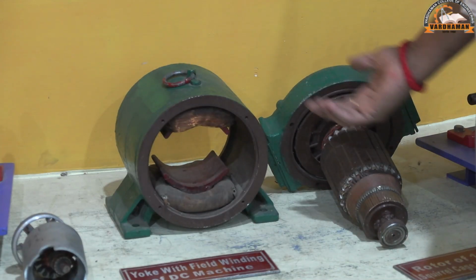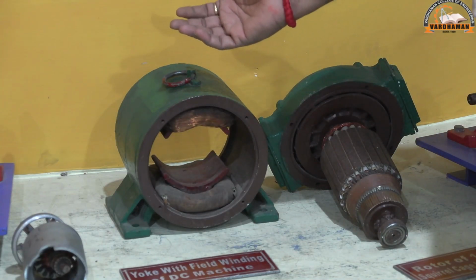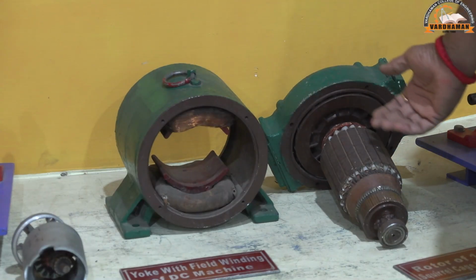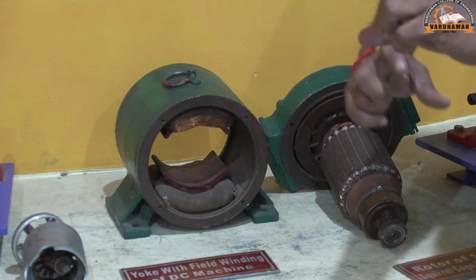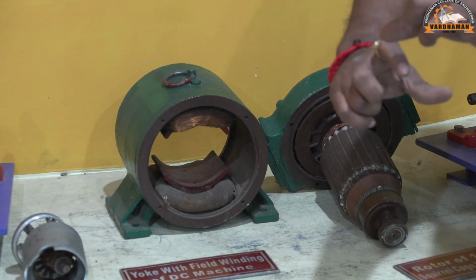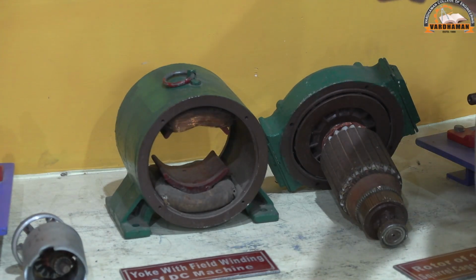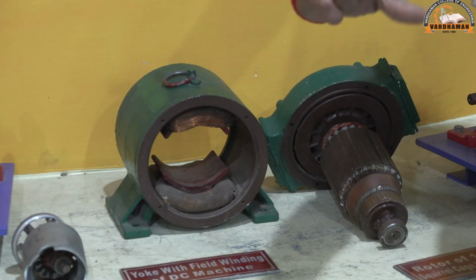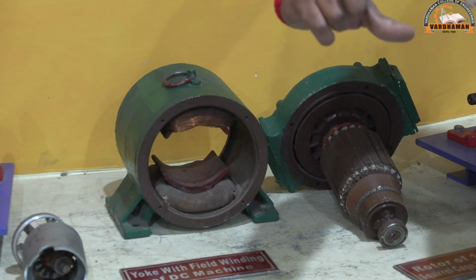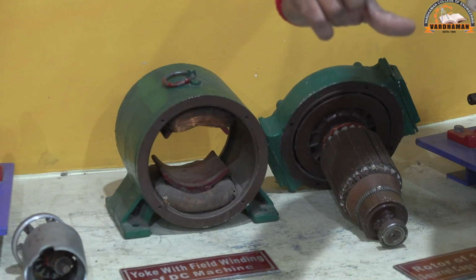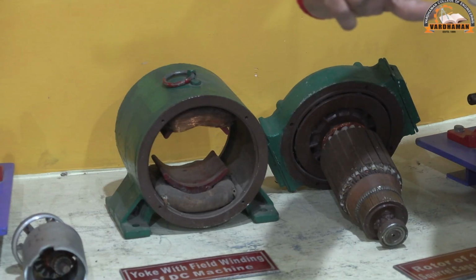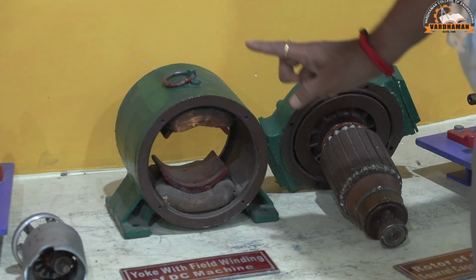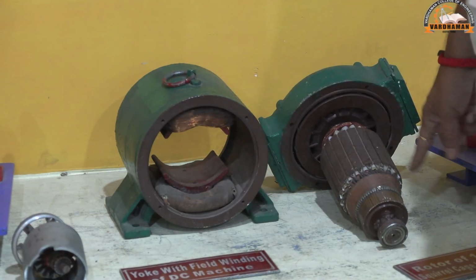So we have another two types of compound motors: cumulative compound motor and differential compound motor. In a cumulative compound motor, there is a series field, as I already explained, which is in series with the armature. If the series field is properly connected, that means Y, Y is connected to A1, A2, it is called a cumulative compound motor. If the series field is reversed and connected to the armature, it is called a differential compound motor. These are the two types of compound DC motors.